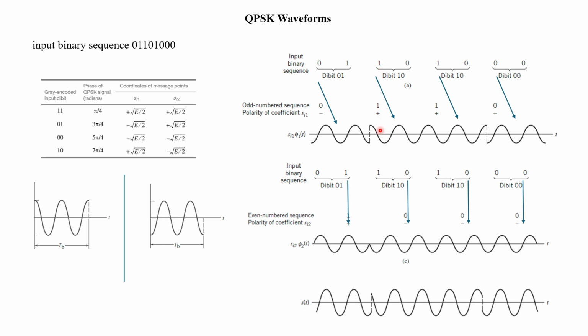I am transmitting, immediately after this Tb duration, the in-phase cosine for Tb duration. Since the next odd bit is also 1, the carrier continues with its phase and it ends here for Tb duration. The next odd bit is 0, therefore we are transmitting the out-of-phase cosine signal.